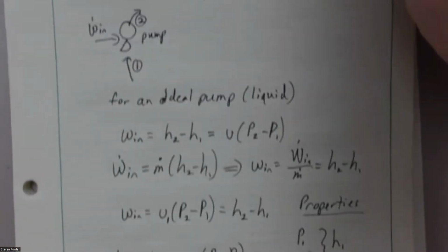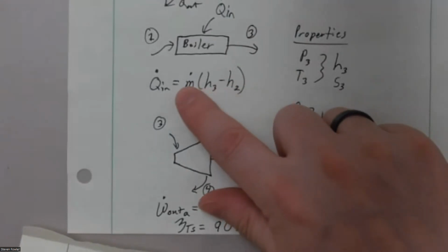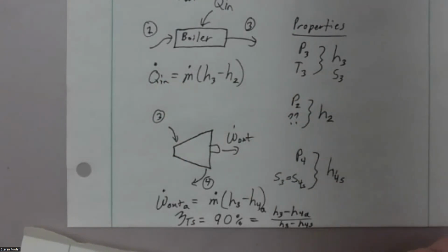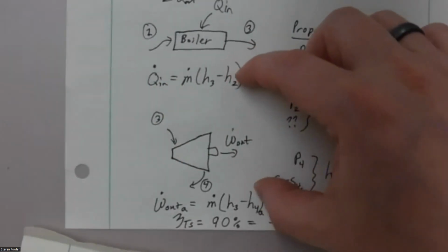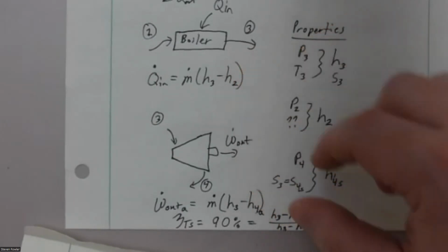So with the second enthalpy in hand, I can go back up to these other equations. Now I know H2, so that comes off the board. Now I need to know m dot, Q dot N, and that would unlock the work out down here. So now I'm down to two equations with two unknowns up here. I'm sorry, 2 equations, 3 unknowns. I'm down to 2 equations, 3 unknowns up here.